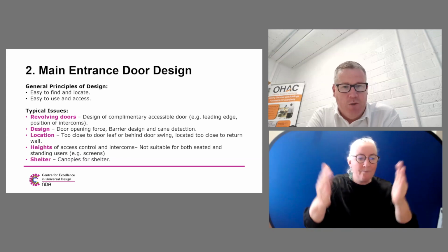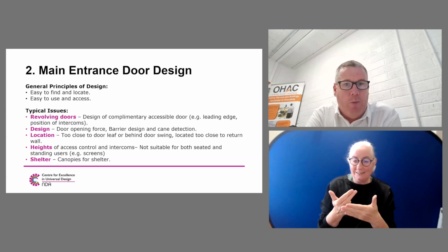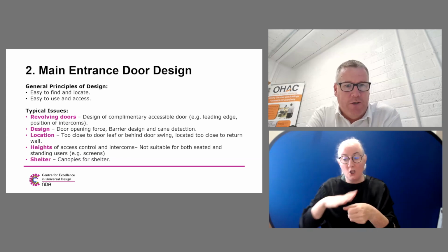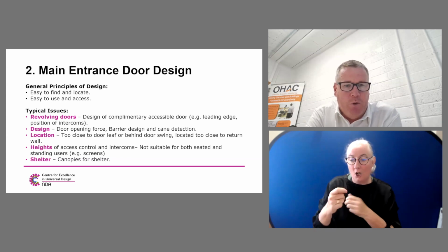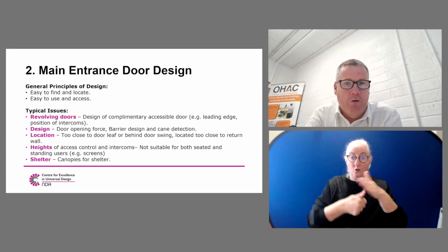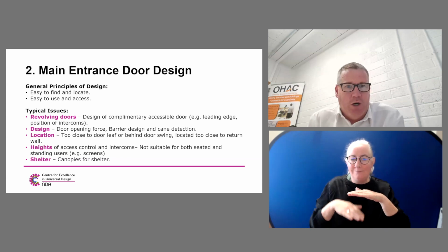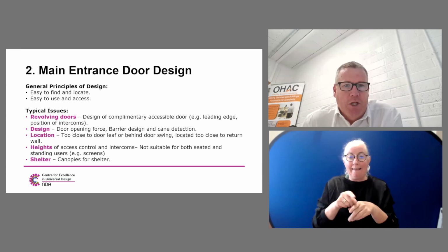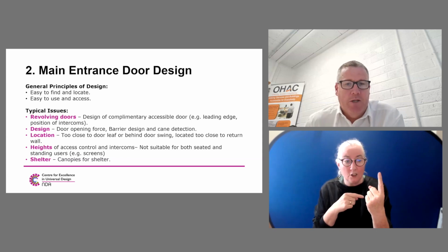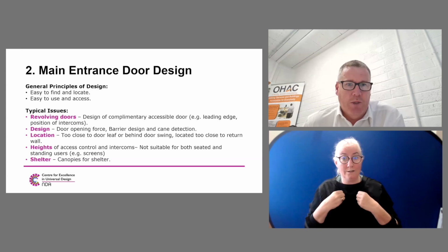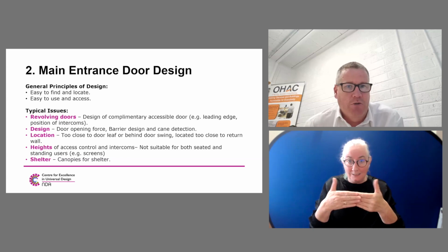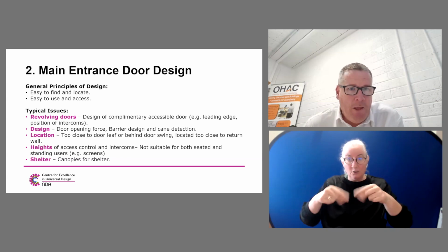Barrier design and cane detection. This has been an issue on projects for a long time, but it's more and more an issue now, where some local authorities are requiring that doors should be recessed if they're opening out onto a circulation route. The local authority wants to reduce the number of barriers or cane detection elements outside the building. So just keep an eye on that one. It may impact on your overall design at planning stage, but also at detailed design stage. So how you design your footpaths outside the doors, so that your doors are recessed out of the circulation route, is one to really watch out for.